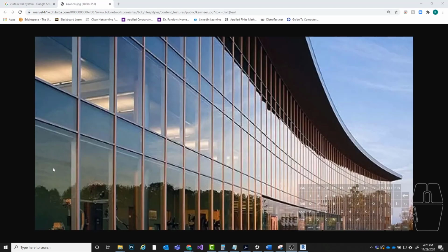We have the curtain wall panels, again, that's the glass. Then we have what are known as curtain wall grids, and these are basically just lines that are used to divide the curtain wall into panels, okay? And we place these lines individually. And then on those lines, we have our mullions. The mullions and the curtain wall grid lines are separate, okay? You can choose to add a mullion to them, or you can choose to not add a mullion to them. And that'll make some more sense as we continue and I show you actually how to make these.